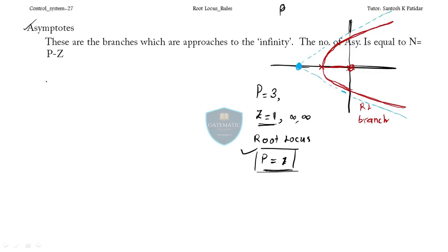See, what I mean is, let's take, you have 3 poles, -2, -1, -5. You have only one 0, that is at 0 itself. Now you have 2 remaining zeros, definitely they will be on infinity. Now what is the number of asymptotes? How many lines do you require to take your RL branches to infinity? Only 2, isn't it?